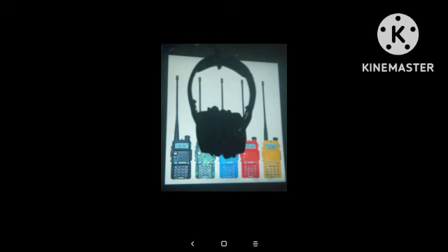Number 55. During a club ARRL Field Day outing, reception on the 20-meter SSB station is compromised every time the 20-meter CW station is on the air. What might cause this interference? Receiver desensitization.